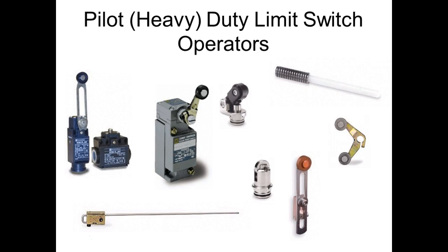So like I said, we got all types of operators. Now what's wrong with limit switches? What are some of the problems you think with limit switches? Electromechanical, exactly right. So these are electromechanical devices, which means what? They fail in two ways. These guys have to make physical contact. Anytime we rub against something, we wear off a little bit, so the operators eventually are going to wear off too, right? Understand? So these guys are going to have to be maintained.